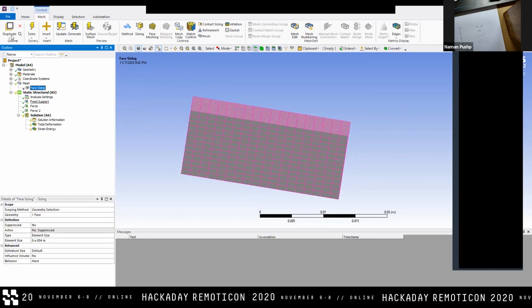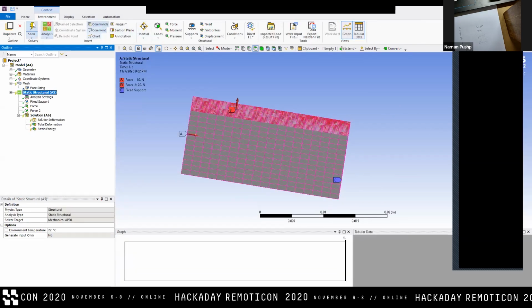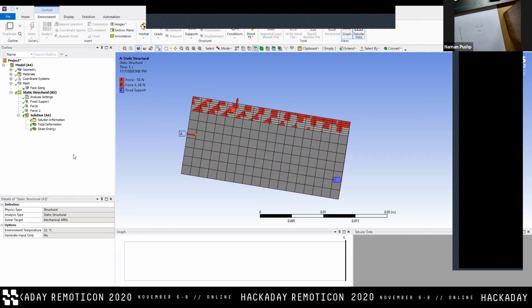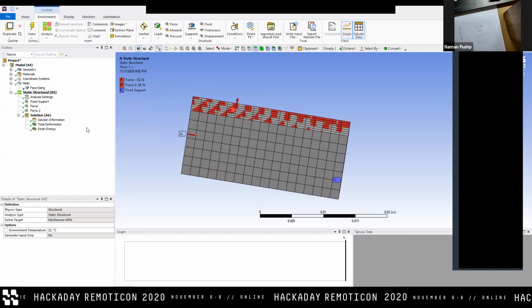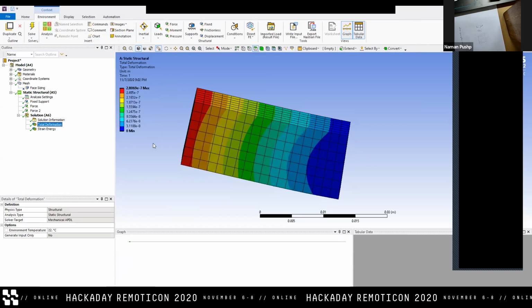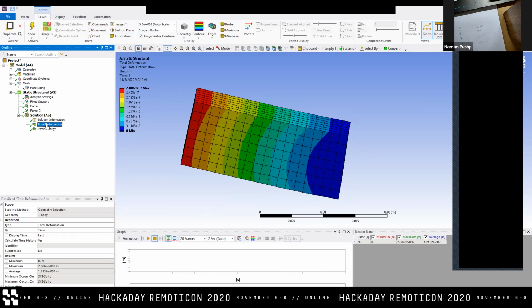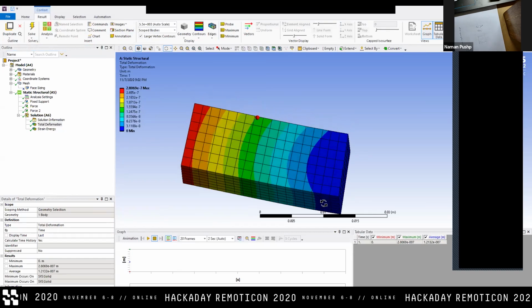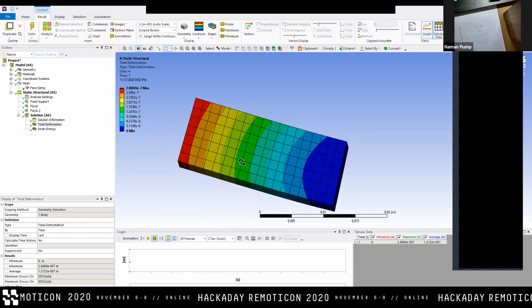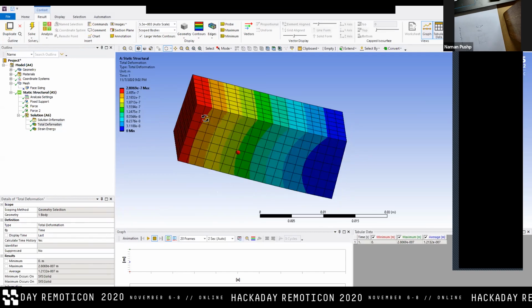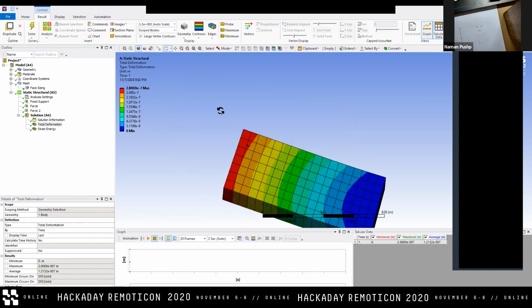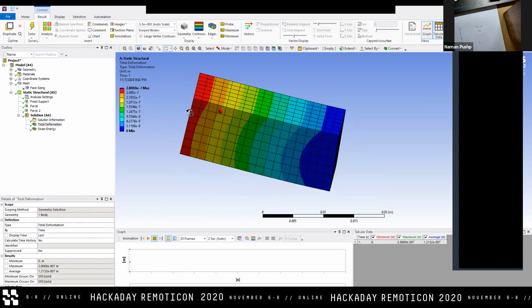You can sort of see the different things can change the results. Here it will probably be minor, but there may be some slight difference in the results. Let's see. So over here you'll get these results. You'll see it looks a lot more different. Now here, instead of being curved, it's a lot more straight because of the mesh. So that's why mesh matters. You get a lot more regular result like this now. So these are the things you can note.